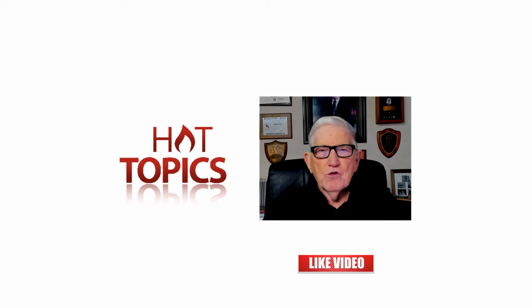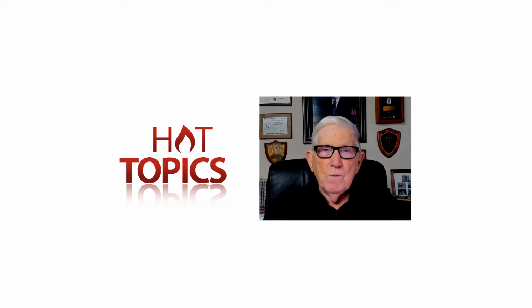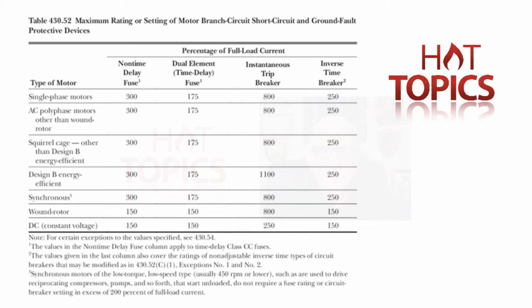However, if nuisance tripping occurred, they could apply the exception 1 and round it up. If still they had nuisance tripping of the overcurrent device, they could go to the exception 2 and apply the maximum percentages in the table, which we will talk about. But notice the table